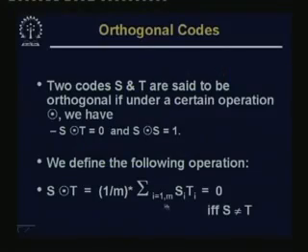If you look at the previous sum definition, the sum of Si is going to be m. You divide that by m, so that will give you a 1. So, S dot S would be 1, whereas for any other code T where T is orthogonal to S, this sum is going to come out as 0. That is how we cleverly assign the codes.